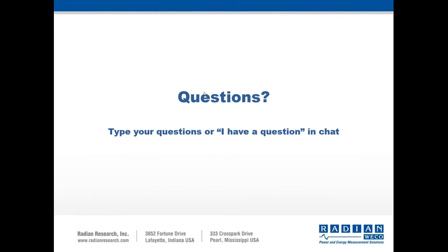So I think it depends on the site specifically. If the meter is going into a service with delivered and received, it might benefit you to test both delivered and received. But if you have a meter programmed for delivered and received that's just going into a typical site where no received power would be there, the delivered testing should cover 100% of what that meter plans to do.